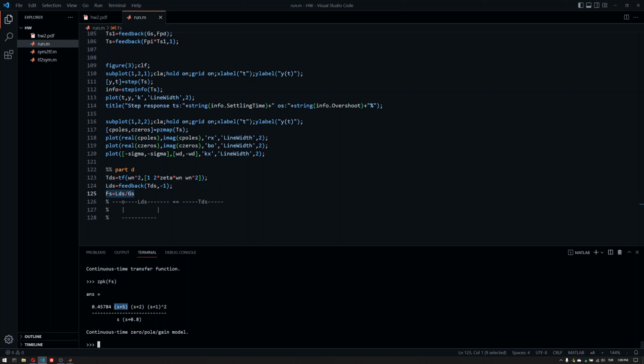Now you can see that it places a pole at 5, and then we have also another pole at 2, and 2 poles, actually zeros. It places a 0 on top of 5, 2, and 2 on top of -1, and places its own poles, adds the gain, and that's basically it. If you use this controller in the closed loop, you will end up in the desired result for this case.